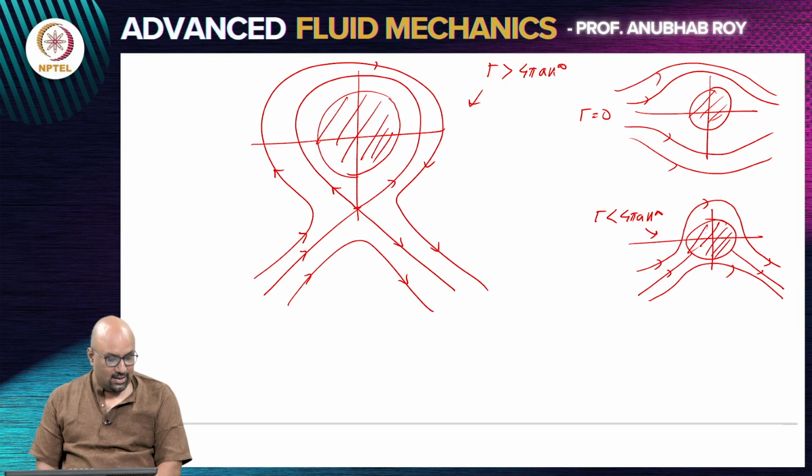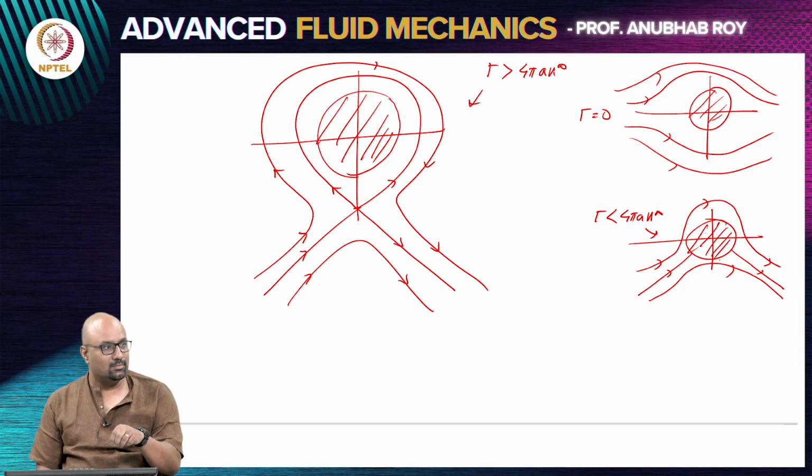So, obviously the flow field is still irrotational. We have added a point vortex, so the vorticity is actually inside the cylinder. The point vortex that we have added, if you think of it, is inside the cylinder at r equals 0. So, the region that is outside the circular cylinder is irrotational. The flow field outside the circular cylinder is perfectly irrotational. So, now the point of doing this exercise is to not just get the velocity field, but also find the forces that the cylinder is experiencing.